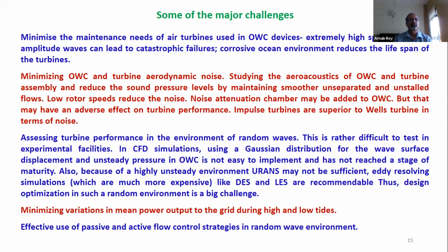research should look at. Then we need to minimize OWC and turbine aerodynamic noise, because very often they are close to the coast, and many of such coasts, especially in populated countries like India, are thickly populated, and therefore there are environmental issues. So studying the aeroacoustics of OWC and turbine assembly to reduce the sound pressure levels, that is the unsteady sound pressure field which is generated by such devices, by maintaining smoother, unseparated and unstalled flows over the surfaces, over the blades, is very, very essential. And usually low rotor speeds would reduce the noise.